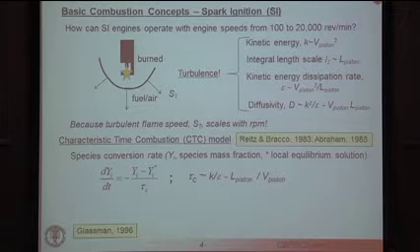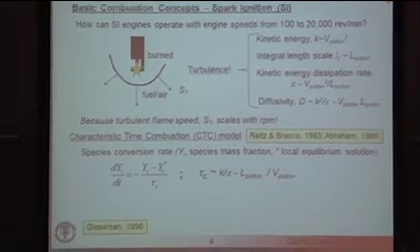So if you want to model this, you have to give a little bit of thought to turbulence. We already spoke about the turbulence kinetic energy. Essentially, if you think about it, the process involved with the air passing through those valves, generating turbulence, is really driven by the piston motion. So the turbulence kinetic energy should scale with the piston speed squared. There may be a constant in front of this. The scale of motion in the chamber is really limited by the size or dimensions of the chamber, so let's just call that L piston here.